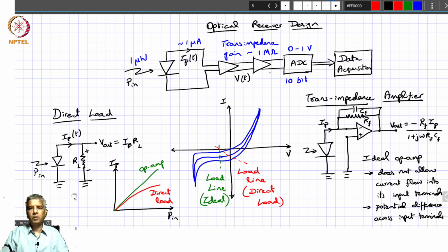So then I would have to put a voltage amplifier beyond that to give me that gain. So what we talked about is 10 power 4, if you want to achieve 80 megahertz bandwidth, then this has to be limited to 10 power 4. So then you will have to limit this to 100. Okay.